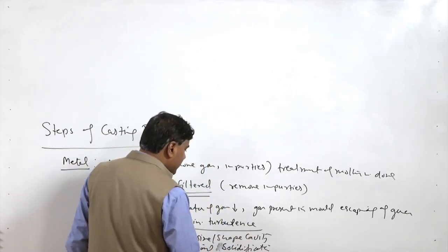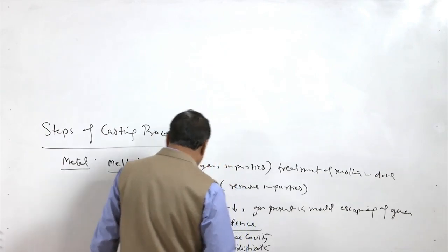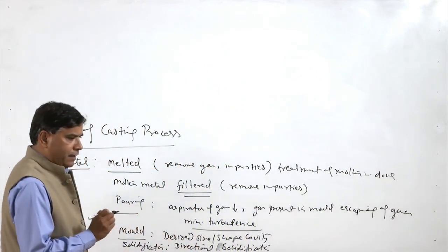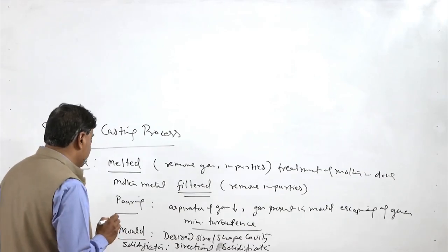So, it is preferred that directional solidification is achieved through the proper temperature gradient within the mold.